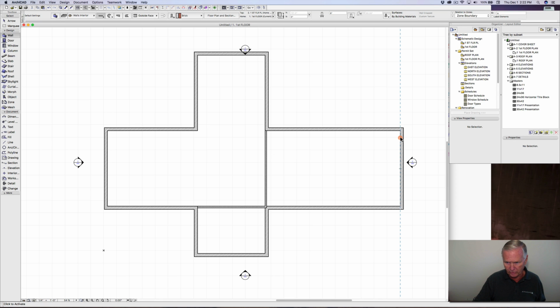Now we'll go over here and hover over that inside of the garage wall, drag a guideline over, D. Now we let go, 24, enter, and now we have a guideline ready for our wall to go in. Now, again, you see we clicked on it, put the walls on the inside. We want 24 feet clear, so we need to go flip that. Again, we can do it by going up here. The other way is to realize that if we had, now I'm going to hit the escape key, if we had started up here with the wall, it would have been on the correct side, and we could have drawn it, and we didn't have to make a change. So sometimes you just got to think a little bit ahead, and you can save yourself a click here or there, and that of course speeds up everything.